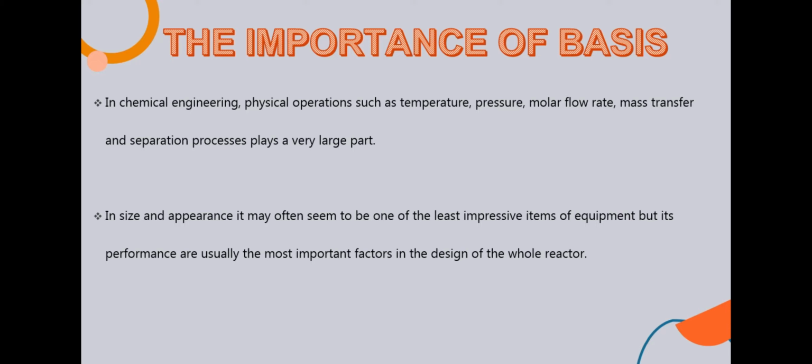The composition of the products must of course lie within any limits of the inlet composition of the process. Thirdly is the temperature, and lastly is the operating pressure within the reactor and any pressure drop associated with the flow of the reaction mixture.